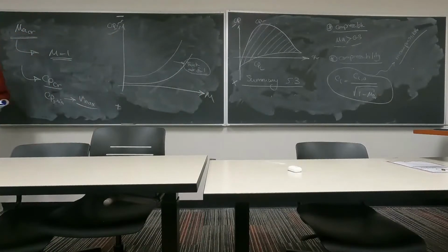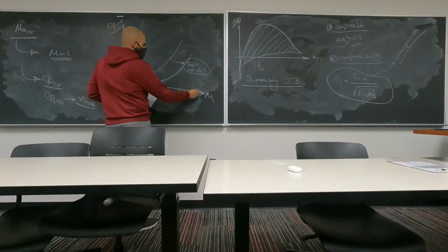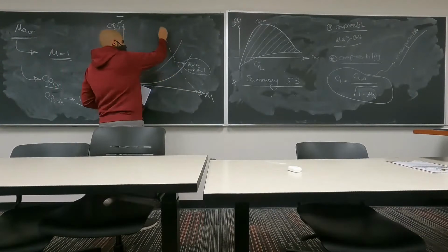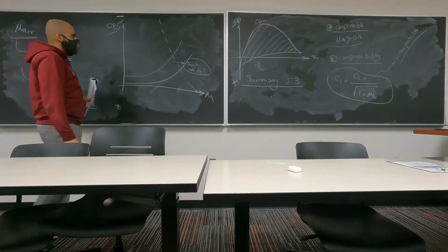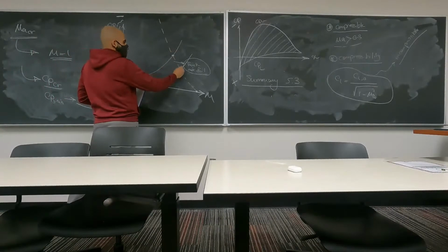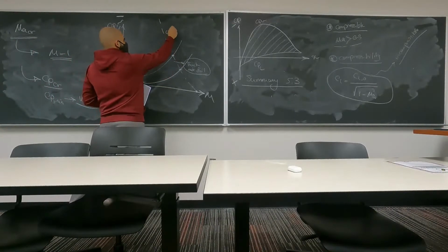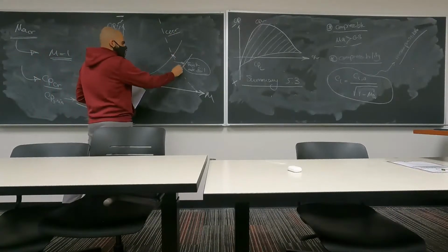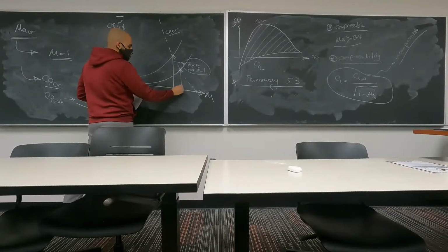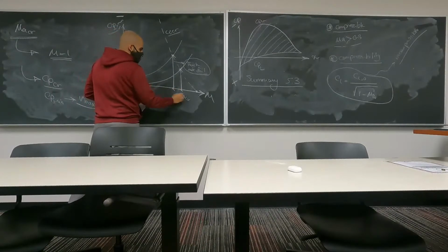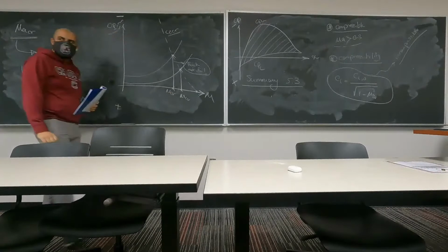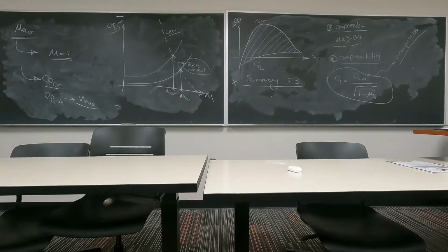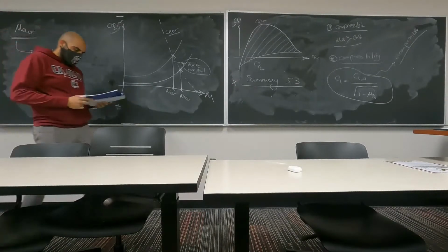And we're actually going to have a critical Mach number line here, or critical CP line. This line identifies the critical pressure coefficient. These values are going to give you the critical Mach numbers for each airfoil. So what was the critical Mach number again? It was the Mach number at which you are going to get sonic speeds on your airfoil.